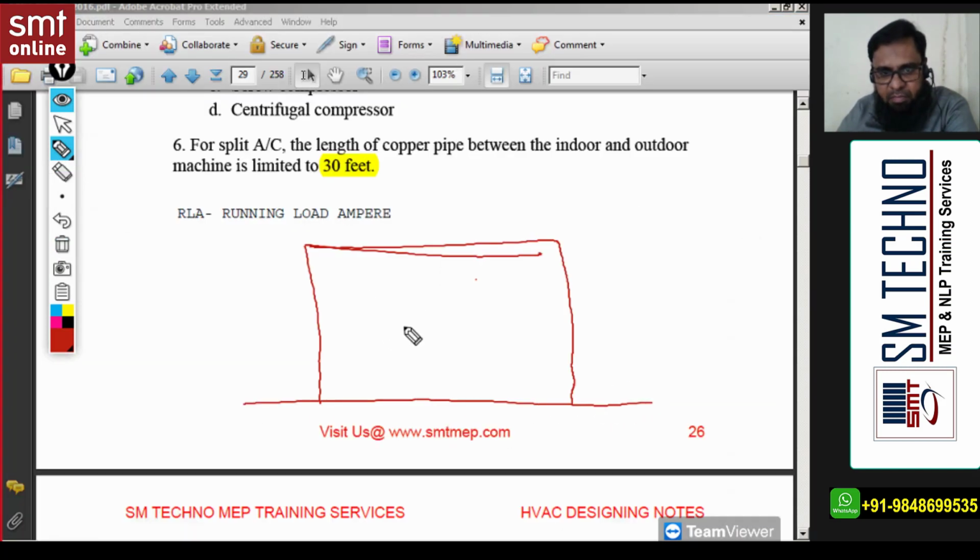wall, and this is the floor level, and on the wall, generally above 6 feet, we will install the high wall. Suppose this is the indoor unit. So here the liquid line and suction line, which will connect to the outdoor, we will not discuss because that is already there in the notes. But the third pipe, here I'm taking from the right side. You can take from the right side or left side, or directly take out from the center through the wall to the outside, as per the option. But for example, I'm taking the right side, and this is concealed in the